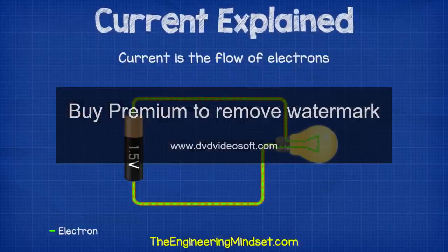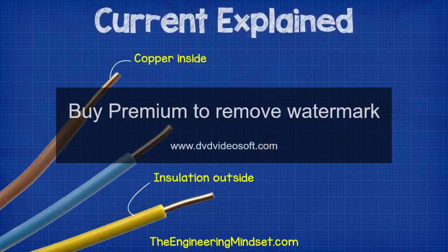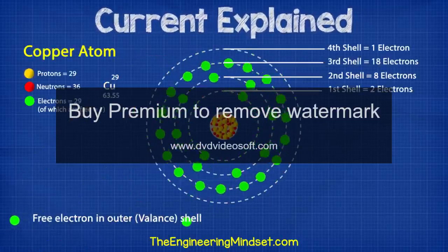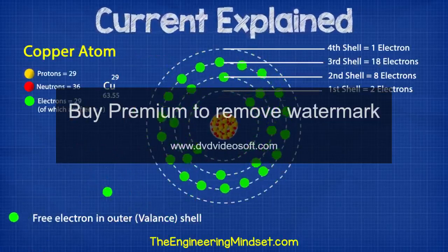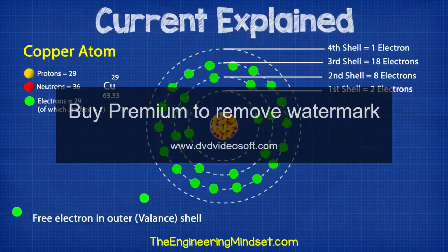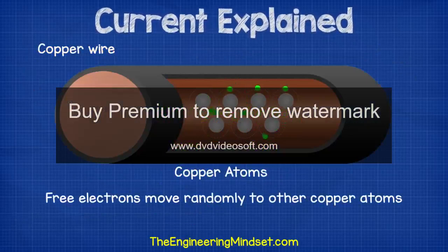Current is the flow of electrons in a circuit. To use electricity, we need electrons to flow in the same direction around a circuit. We usually use copper cables to form the circuit because the atoms that make copper have a loosely bound electron in their outermost or valence shell, which is free to move around inside the metal. This free electron is very easy to move, which is why copper is so popular. It's so easy to move that it will naturally just move to other copper atoms by itself, but this occurs randomly in any and all directions, which isn't useful for us.